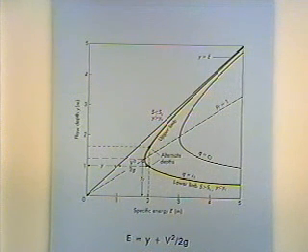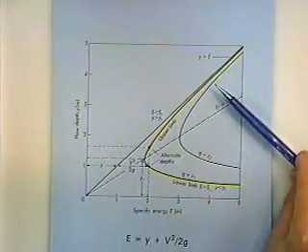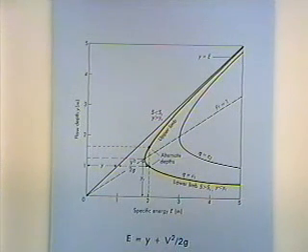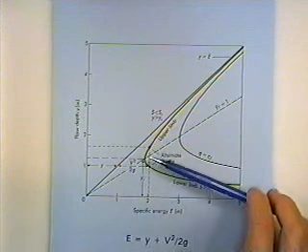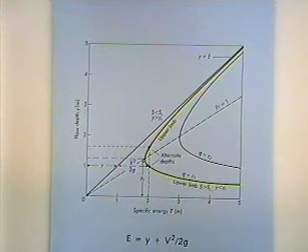Now, at some point we're asymptotic to the 45-degree line, and we can call these alternate depths. We talk about hydraulic jumps, and we will a little later. These will be pertinent to us then. If we take the concept of the specific energy being a minimum and find the depth at which the specific energy is a minimum, we can go through some manipulations and derive an equation which is used commonly to solve problems.